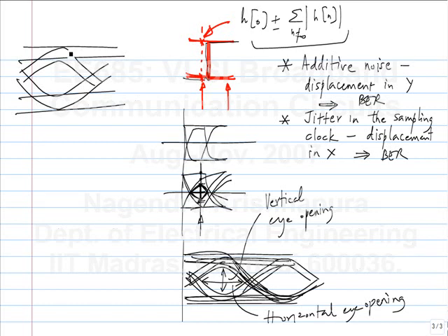So this is the eye diagram, one period of the eye diagram. One period goes from here to here. So it always looks like this, and the eye diagram is periodic because in every part you include all possible bit patterns. Okay, the data is not periodic, but you have random data, and then you take 2 bit intervals and overlap them. So the eye diagram itself is periodic. Is that convincing? Because you take all possible bit patterns for every period here, right? If you take an eye diagram from a long enough bit sequence, you will have a periodic eye diagram. Think about it. If it's not convincing, I can explain it further.